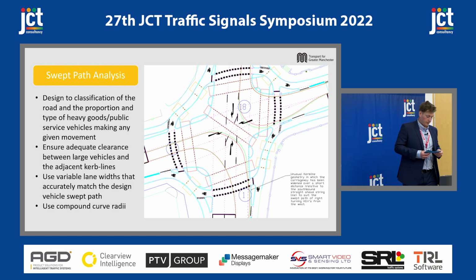Also, the use of compound curve radii has a lot of benefits. These include slowing traffic down, liberating valuable footway space, creating shorter pedestrian crossings, and also ensuring that the pole that has the right-hand push button can be safely located and used by visually impaired users.